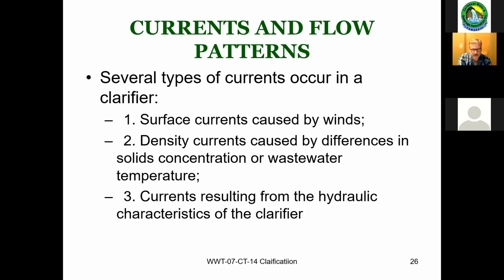And the hydraulic characteristics of a clarifier. When they talk about flow patterns and hydraulic characteristics, they're basically saying removal rates in that clarifier and how you would attack that. You can take clarifiers either in or out of service to change the length of time the hydraulic loading has on those clarifiers.